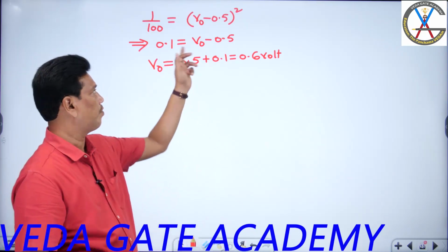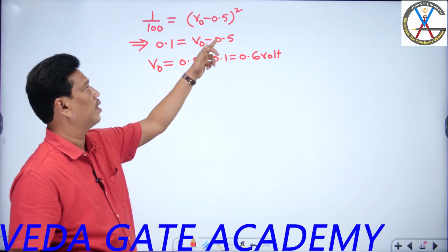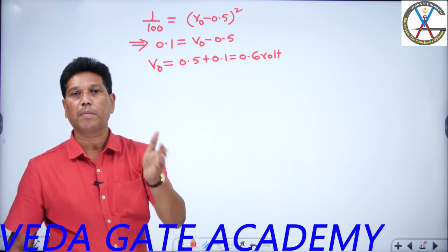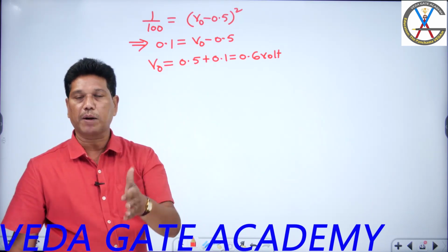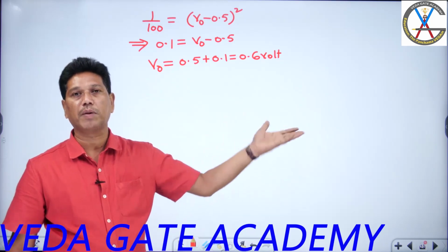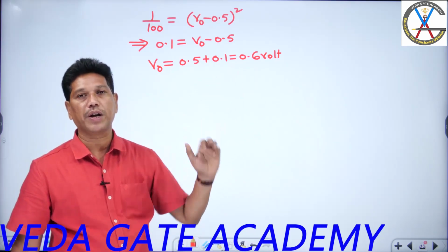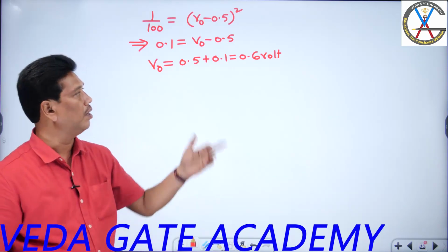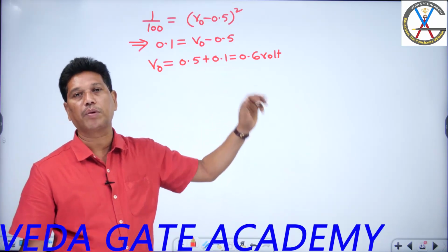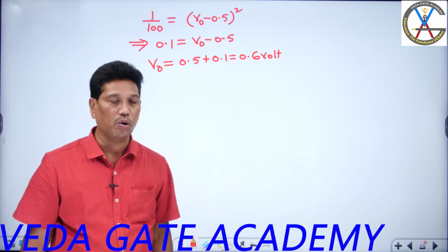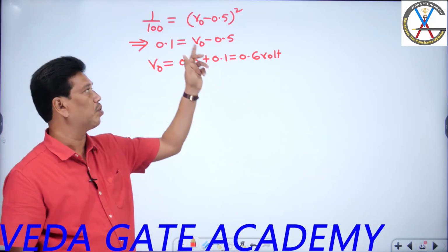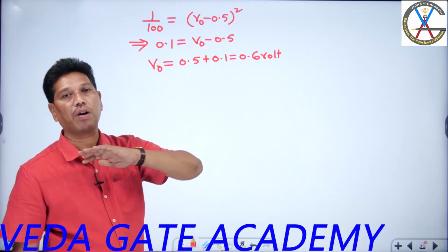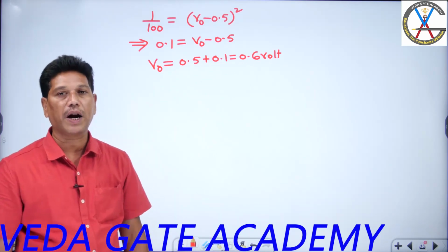Confirm my option. So if I take plus or minus 0.1, that becomes 0.6 or 0.4 volt. Suppose we take 0.4 volt, the corresponding V0 same as VGS would be less than VT, the threshold, such that the body is not in conducting mode. That completely indicates a wrong condition for your statement. You already learned saturation mode, so that should be false at that time. So output V0 of 0.4 volt is not allowed. The only answer is 0.6 volts, sir.